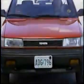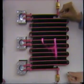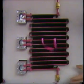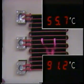The refrigerant in the condenser is cooled by the air while the vehicle is running, or by the cooling fan of the vehicle. Let's measure the temperature of the refrigerant at the entrance and the exit of the condenser. As you see here, the temperature is lowered substantially by the condenser and the refrigerant is turned into a liquid. In other words, the refrigerant discharges the heat that it collected from the air in the passenger compartment to the outside of the vehicle.